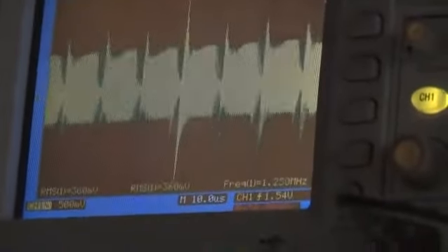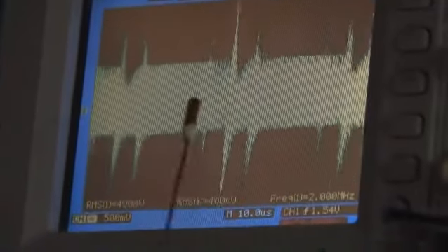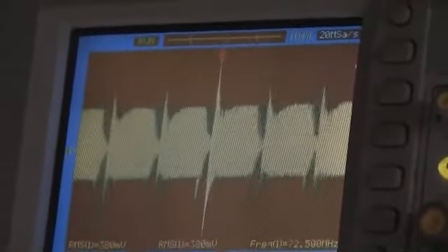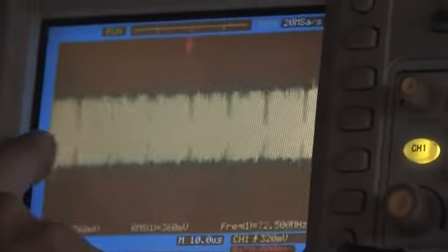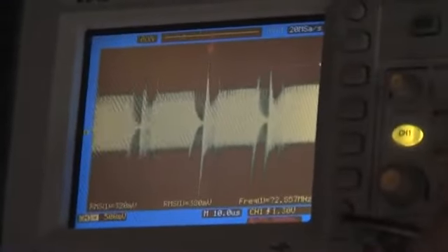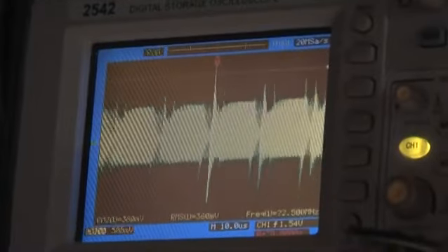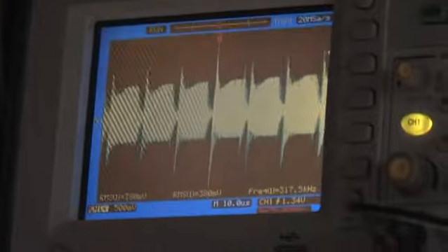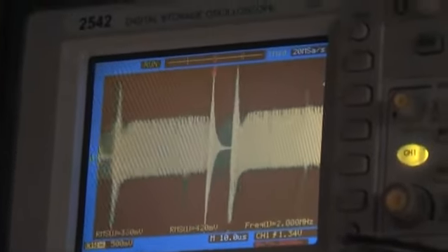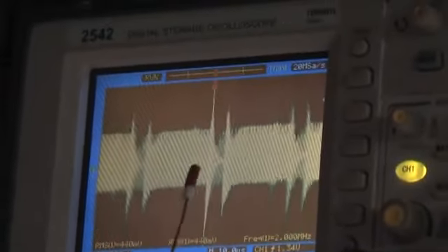When it goes down to the lower frequencies, see the gates? It's kind of hard for the scope to trigger on it. It doesn't know. We can force it, but it's not going to do it. And once we have our trigger line down here, we're not going to be able to see it until we get it to where it can catch a peak. You can see it in that. So there's our packets, see? And the gates in between.